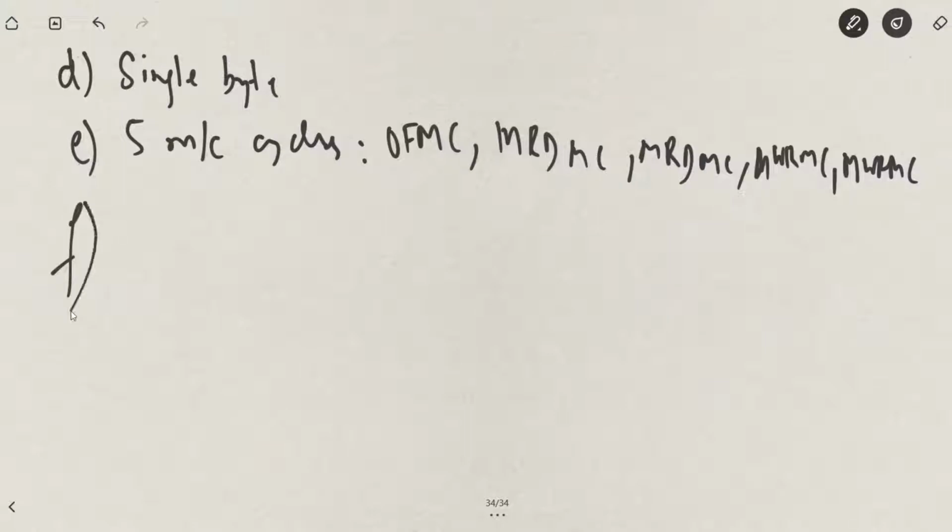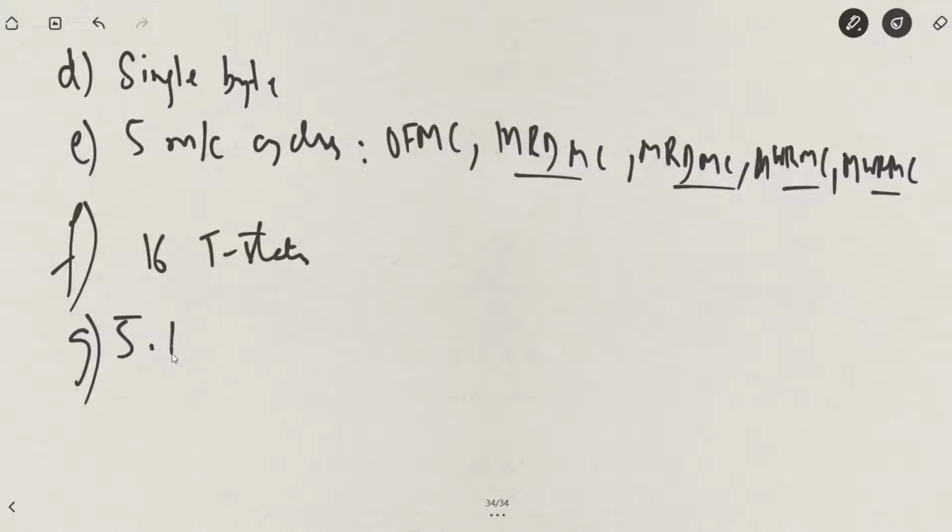Now the opcode fetch machine cycle here will be again 4 T states. So 4, 3, 3, 3, 3, that is 16 T states. At 0.32 into 16, that is about 5.12 microseconds. There is no variation of this; it exists as itself only.